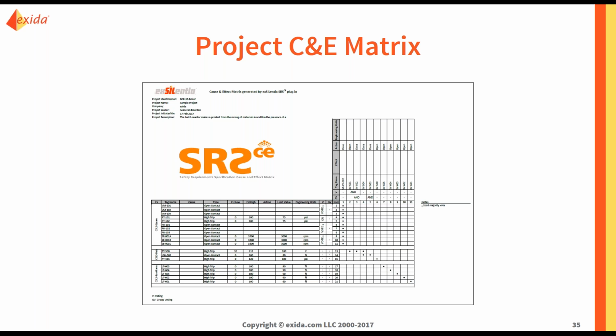And the standard does mention having a cause and effect matrix or an overall description of the SIFs and their inputs and outputs. So this is a nice way to do that. You can, as I said, put a written description into the cause and effect matrix as well.